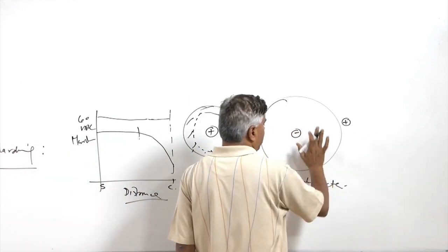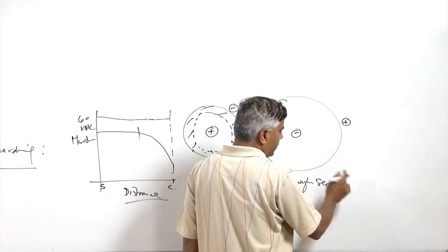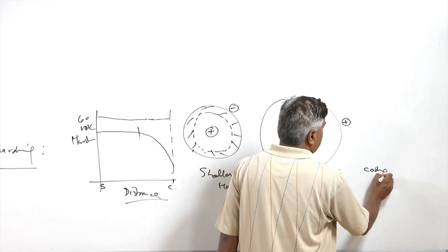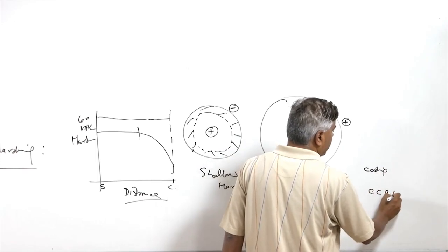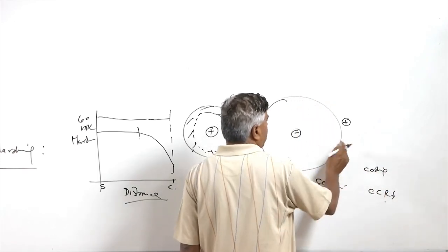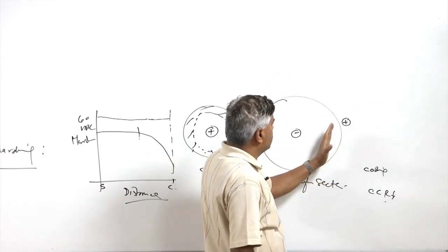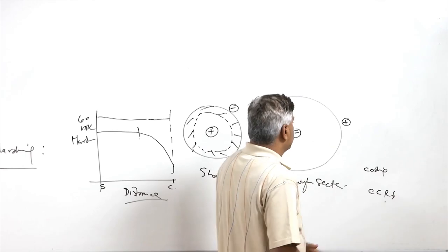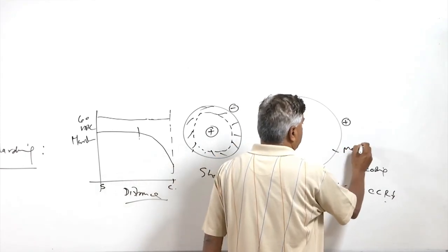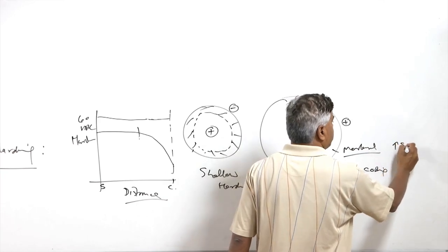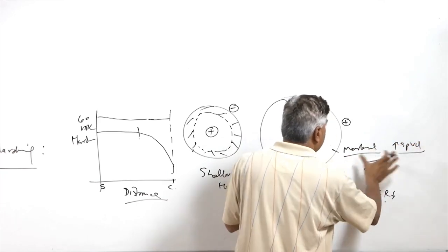When the through section hardening is done, the cooling rates are high and the CCR, critical cooling rate, is low. In that case, as soon as the surface comes in contact with the quenchant, it is cooled down first and it transforms into martensite, which occurs with an increase of the specific volume. Since it is very hard and brittle,